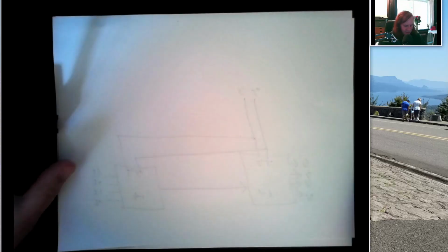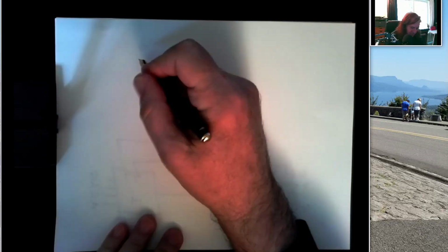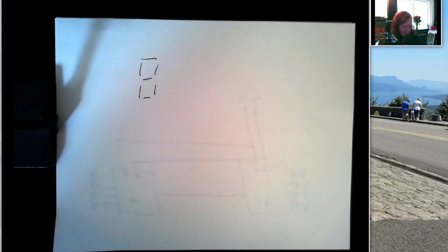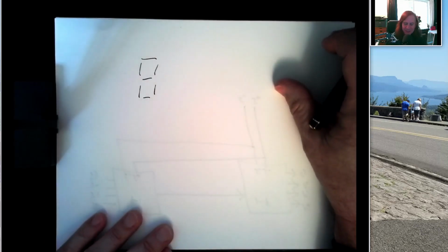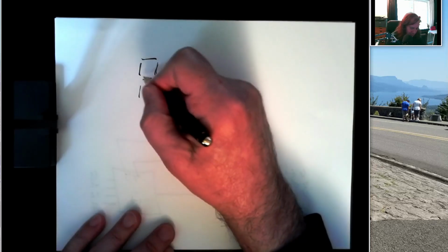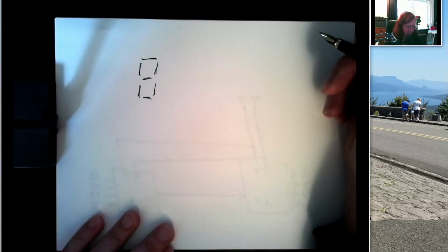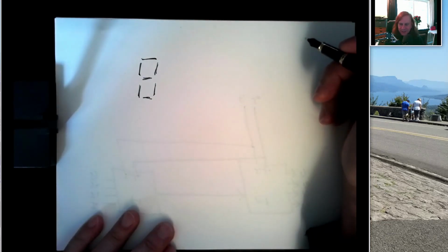All right. So last piece I want to talk about is something called a 7-segment display, and you may have seen these in TV or elsewhere. 7-segment displays are these little devices that basically contain multiple LEDs oriented in these horizontal and vertical directions, and they're set up so that by turning on certain combinations of these, you can make the display look like it's displaying a number, or in some cases a letter.